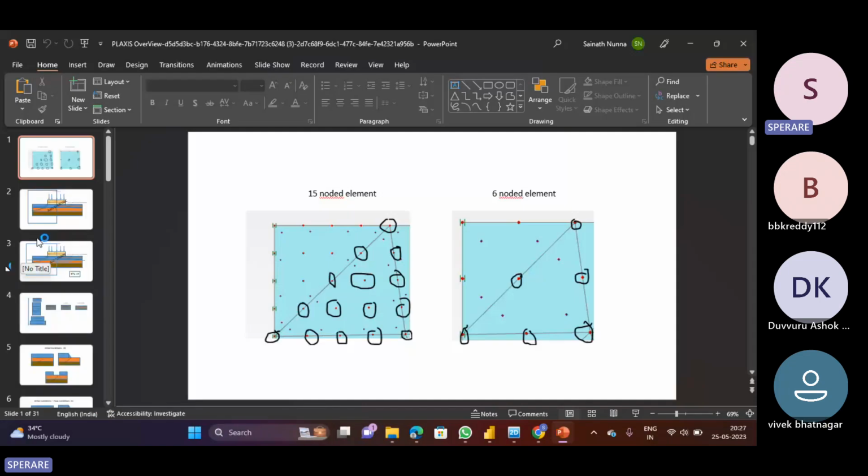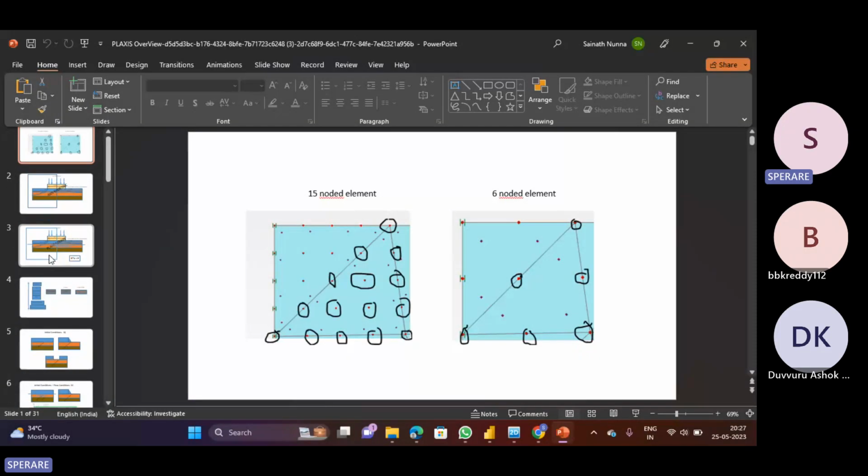So it will come back when there is a huge, very big structure at the side. In those cases, you can assume your boundary conditions as a free field. But when it is not a very huge structure, and I don't want to carry the vibrations further, I would like to nullify them. I'm not interested in how it is spreading and how it is affecting. Then in those cases, I can go with the viscous boundary conditions.